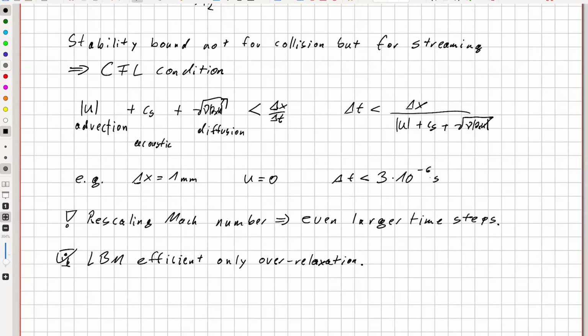So in this case, how will we choose the delta x and delta t? They need to be the same, right? How do we choose the delta x and delta t? Okay, so you choose the delta x by how you think here. Usually you choose your delta x by the thickness of the boundary layer that you expect, for example.